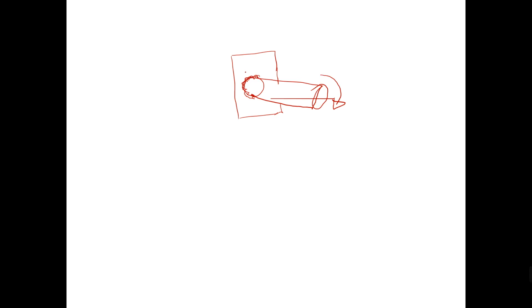If you see the weld, this material is trying to slide on the weld in torsion. So this is torsion stress in the weld. With the same component, if you apply load in this direction, this joint will try to separate in this direction, or the weld will try to break outside of this surface. This end of the part will try to come out of this joint, so that will be the bending stress.